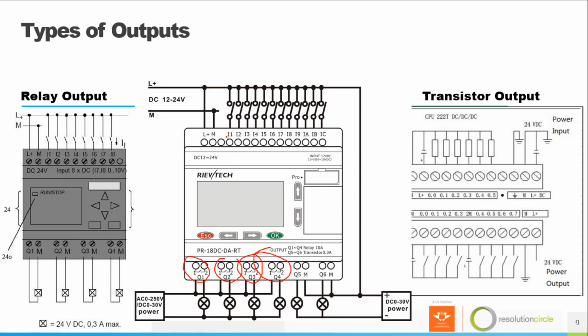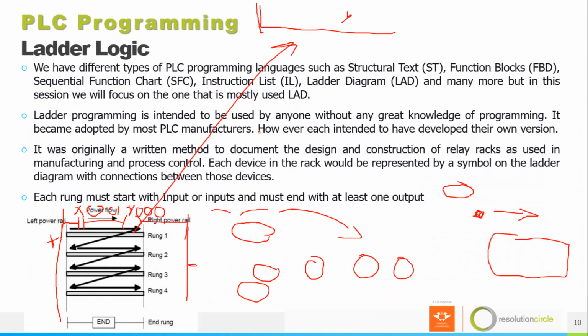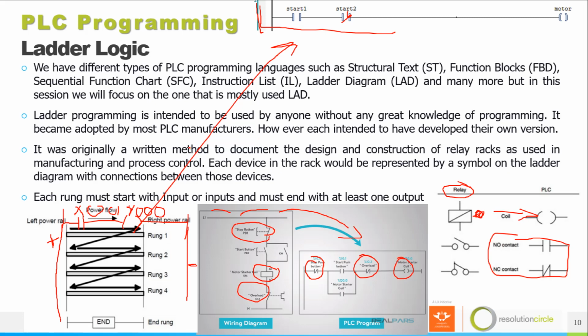Also with your input, you will have to give them addresses based on the particular software that you are using. Addressing differs with the software that you will be using. Okay, so for my start, the address will be X001. My output will be Y000.